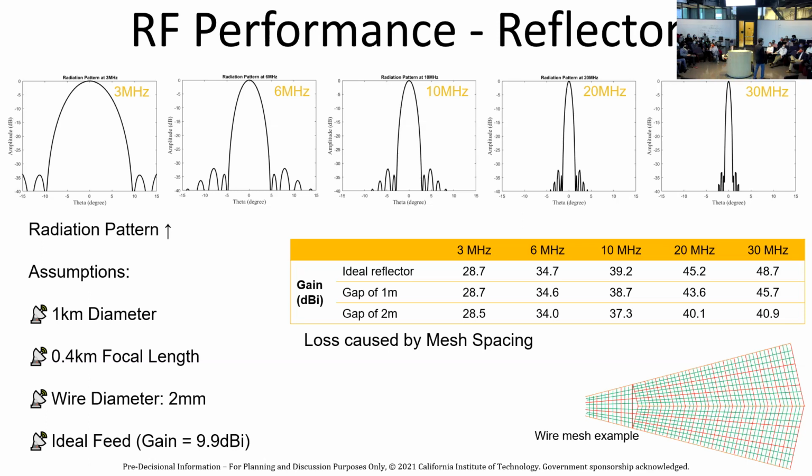There's this rule of thumb that if you want to do any measurement in any wavelength, if your holes are smaller than lambda by 4, so lambda is the wavelength, more or less the wavelength, the signal, the RF or the electromagnetic spectrum will not see those holes. That holds true in optical, in any electromagnetic spectrum. So that gives you an upper limit of my holes in the fishing net could be 2.5 meter cross 2.5 meter. So just think of how thin this mesh is.